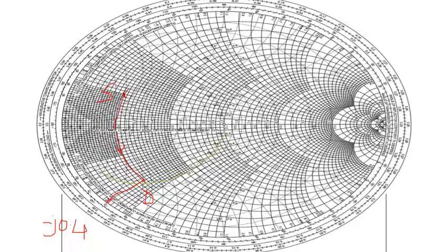Your source value, if you remember, was your solid arc. That value was plus j.2. So when you solve it, it becomes destination minus source: minus j.4 minus j.2. Answer becomes minus j.6. The value of this capacitor, being a series capacitor, it is 1 upon omega c.